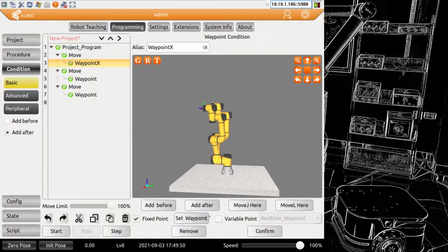So let's check when we are looking in the graphics. We see here a first waypoint. Let's do a move J here. Okay, we have this one which we programmed, move J here. Okay, it's the second position. Okay, and then we have a third waypoint, which we haven't specified yet. So it essentially took the same position as the last one.